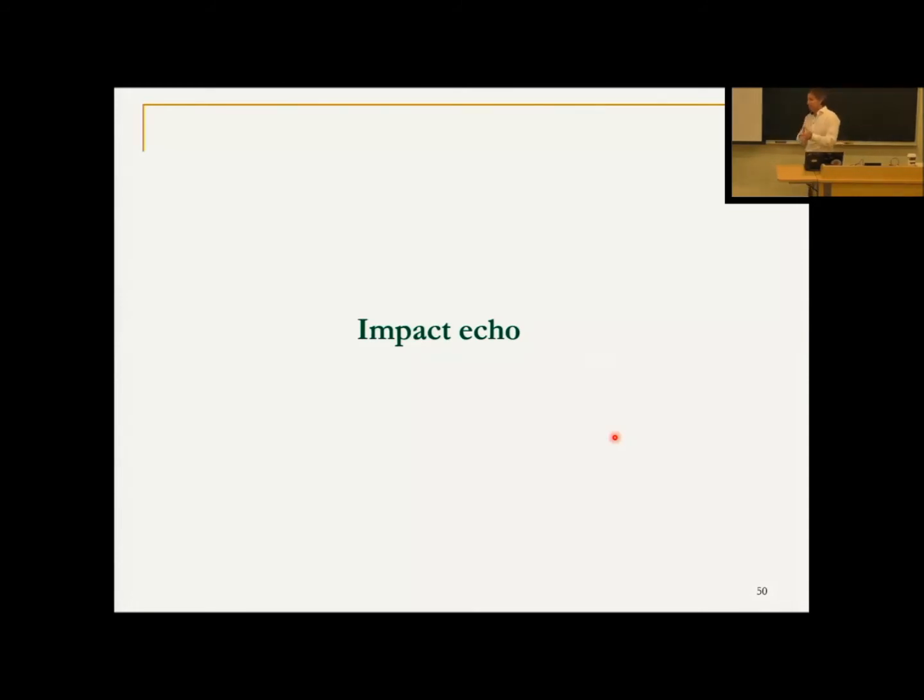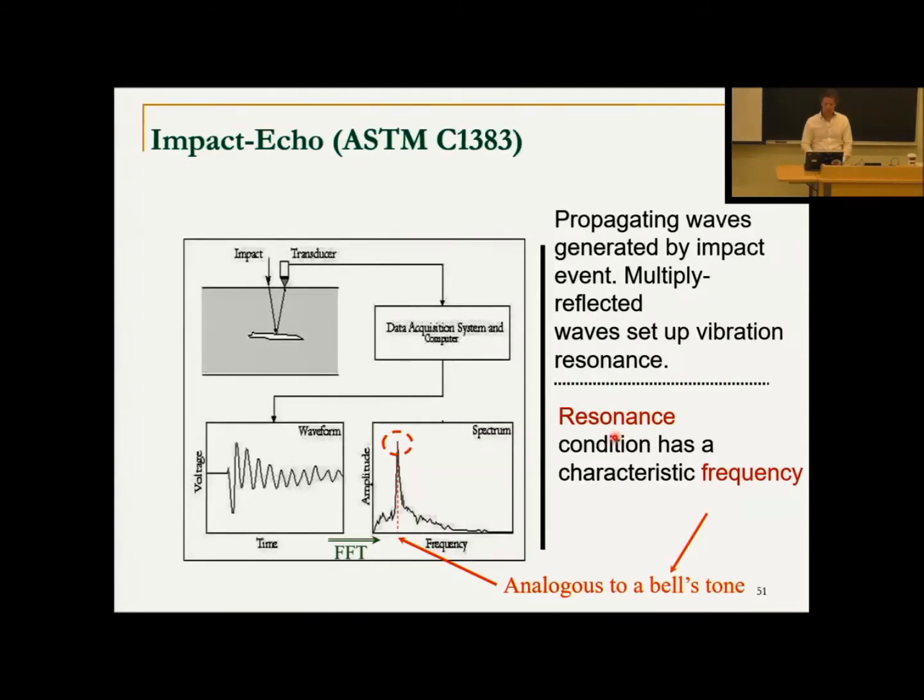And when I was talking about sounding, remember we were tapping and letting this drum head resonate, and then listening for the pitch. I said, remember this for when we talk about impact echo. So my suggestion here is that impact echo is automated, scientific, quantified sounding, right? So instead of just tapping and having an inspector say, oh, that's different, I will mark it, why can't we tap it